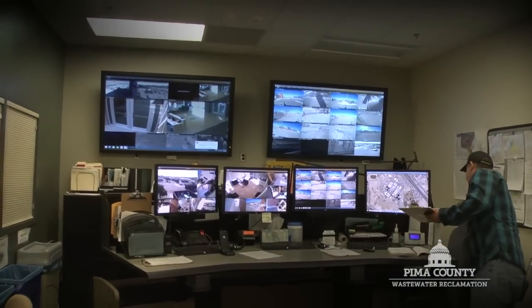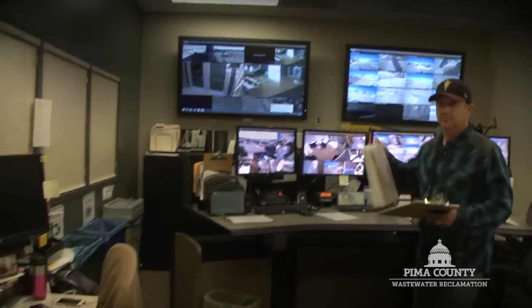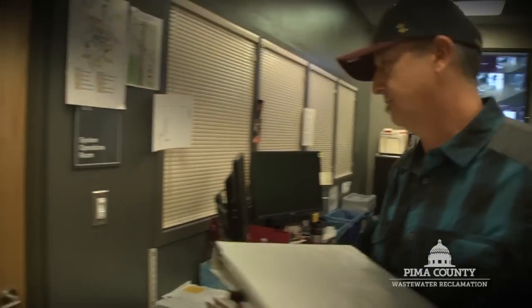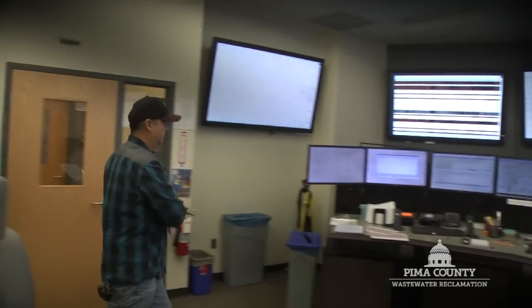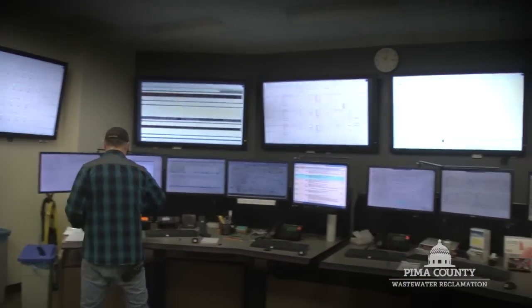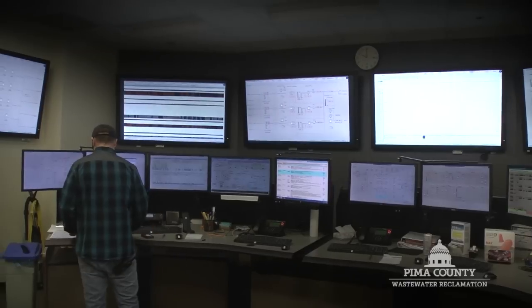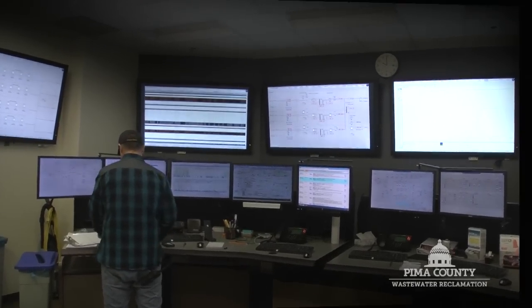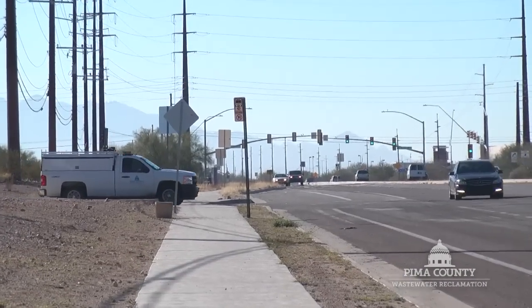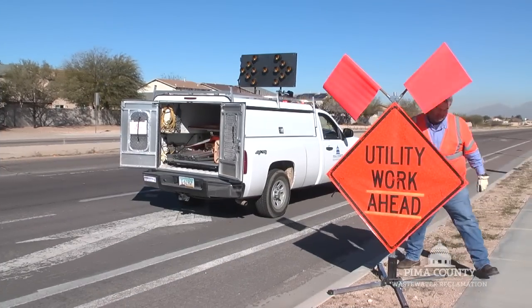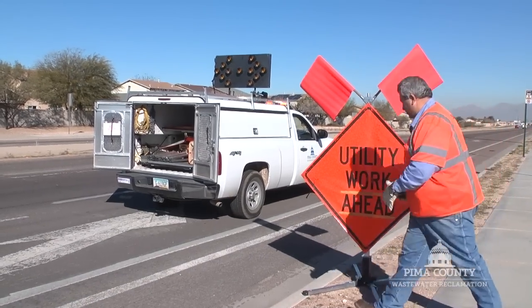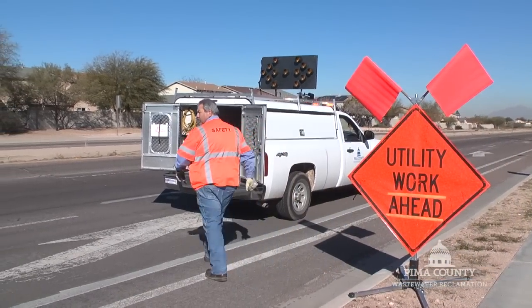After normal business hours, the calls will be forwarded to the Operations Control Center, otherwise known as the OCC. The OCC personnel will then document the lane closures until the conveyance staff return to their posts the following business day. The traffic control supervisor will then begin to place the advanced warning signs, being aware of their surroundings and oncoming traffic at all times.